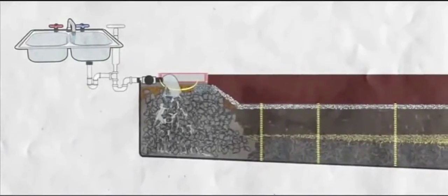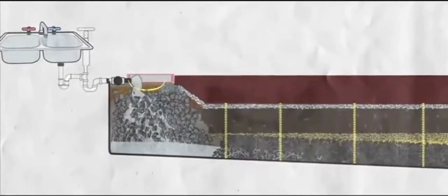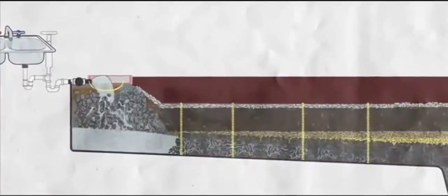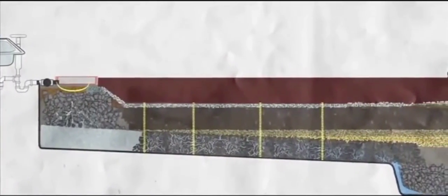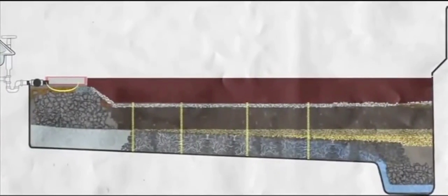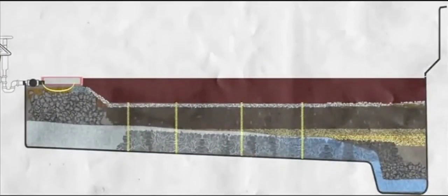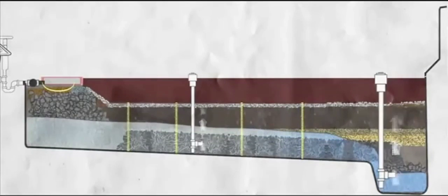Consequently, grey water is channeled through a filter or digester for grease and particles, then sent into an indoor deep rubber-lined botanical cell. A botanical cell is a built soil ecosystem that consists of various soil layers. The first layer is composed of gravel, to allow water to flow and provide good aeration or oxygenation, preventing nasty smells.